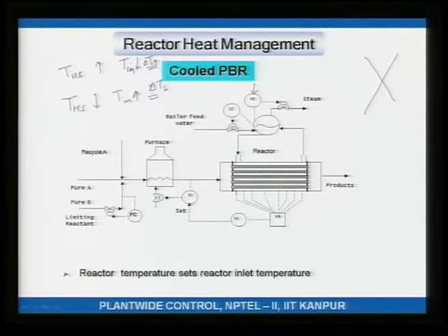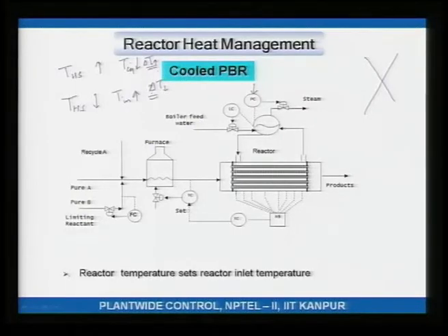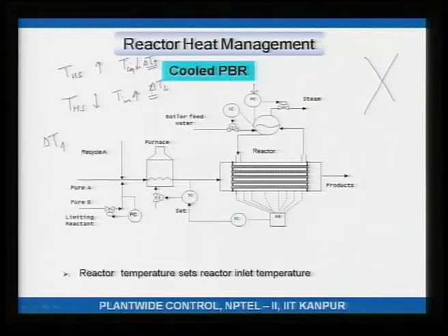Do you think these two changes in opposite directions, one case is increase, the other case is decrease, will be the same? You see, intuitively, since it is more difficult to put out a fire than to light a fire, you will find that delta T when the hotspot temperature is increasing, the amount of change in the temperature at the reactor inlet that you require, is actually much greater than delta T when the hotspot temperature is decreasing, magnitude wise. Okay. So, if the hotspot temperature is increasing, I will have to reduce the temperature by a large amount. If the hotspot temperature is decreasing, I have to increase the temperature only by a little bit. Okay. This small versus large change in the reactor inlet temperature is due to non-linearity.